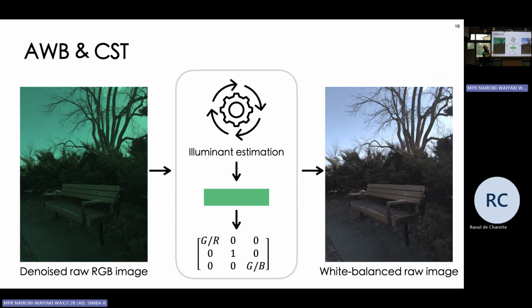So what I'm saying right now is the common practice in industry, or even in academia, where anyone follows the standard camera ISP. We do it in this way. Some of the steps are not perfect, like this one, where we assume it's just a global vector. If we are interested in doing that perfectly, then we need to do white balance especially, like correcting this region differently than that region.